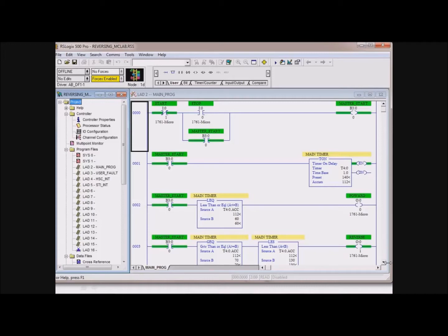You can buy counters that would count a relay contact for you. But then you have a problem: how am I going to keep up with that information? How am I going to do math with that? Well, a PLC would do all the math for you. Not only would we have the ability for it to keep up with the number of entries, we could have it keep up with the number of exits, and then we could subtract the two with a PLC and come up with the amount of rejects, right?